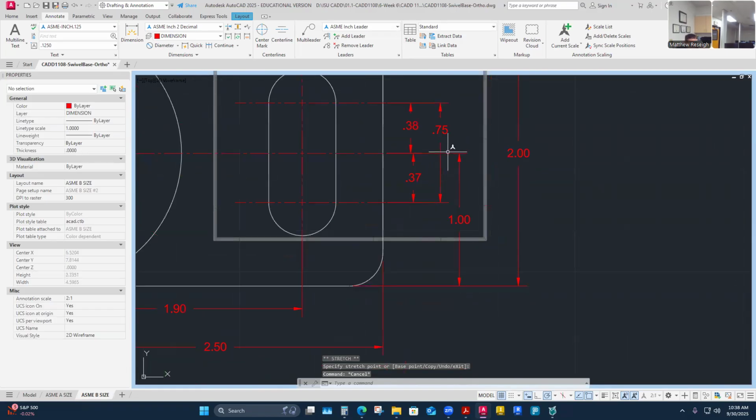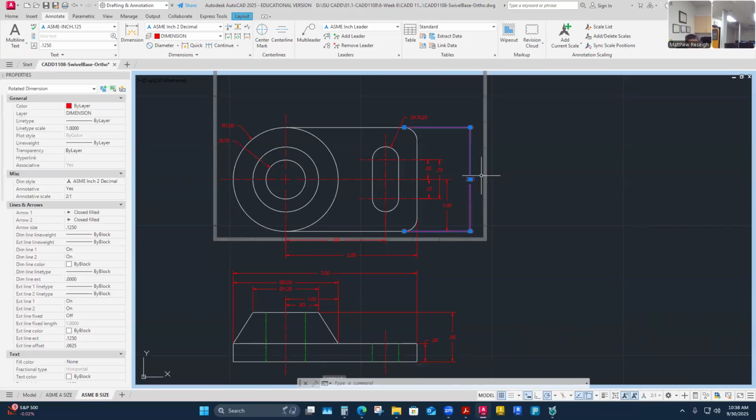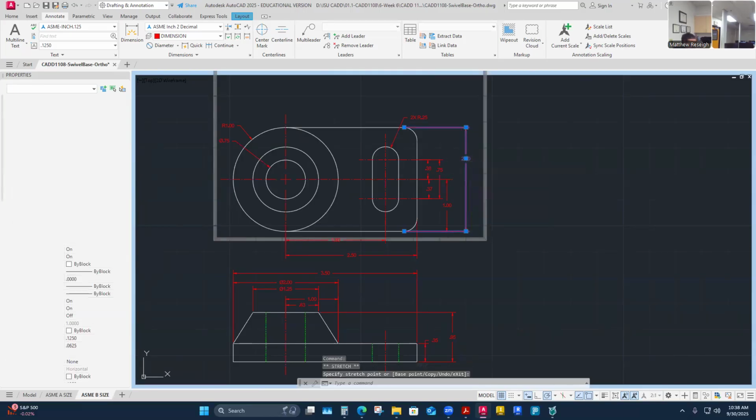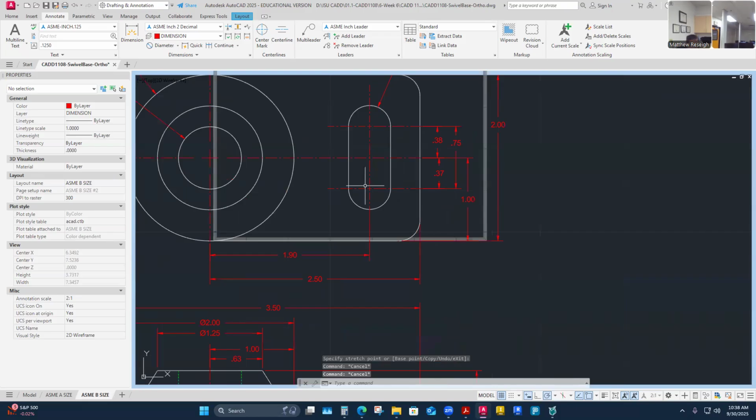I'm definitely going to cut this extension line around that dimension line when I get to cleaning that up really good. Right now, I'm just reanalyzing if I feel like I have everything and how things are going to stack up. But I think I've located this. Yeah, I've got a through axis. It's one reason why it's critical to pull those throughs, because if I'm going to dimension in one spot and I've got a really long slot, but I want it to be axially aligned down a center line, then make sure those center lines pull together from one of the radiuses to the other. That's why I've made this critical move to pull them together. That way one dimension is sufficient. I've chosen this as my control dimension.